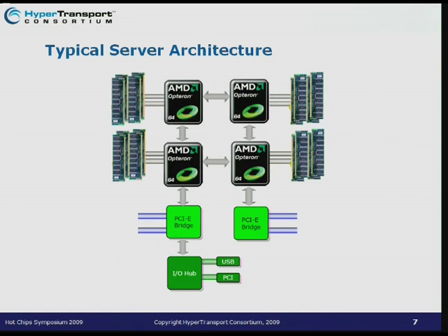So a typical server architecture today basically consists of multiple motherboards, each of them having multiple processor sockets with DRAM slots and also some peripheral devices and controllers. Those processors allow access to local memory as well as remote memory, and also access to multiple peripheral interconnects in a relatively simple way and with low latency. And this is where HyperTransport fits very well, because it allows the coherent access of local as well as remote memory, as well as access to all of those peripheral devices, as well as bridging to other technologies like PCI Express or USB or serial ATA or whatever.